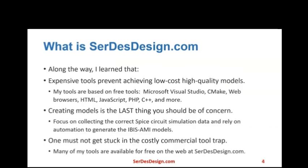Along the way, I learned that expensive tools kill all chances you have of achieving low-cost, high-quality IBIS-AMI models. My tools are based on free tools: Microsoft Visual Studio, CMake, web browsers, HTML, and so forth. I learned that creating an IBIS-AMI model should be the last thing you concern yourself with when it comes to creating IBIS-AMI models. Focus on collecting the correct circuit simulation or measurement data, and use automation. My tools rely on automation to generate models from measured and simulated data.